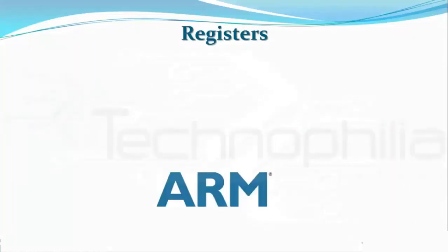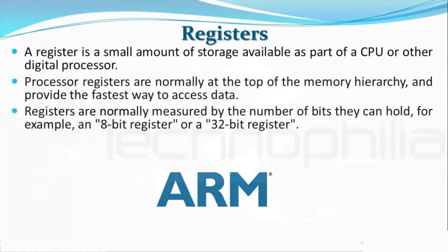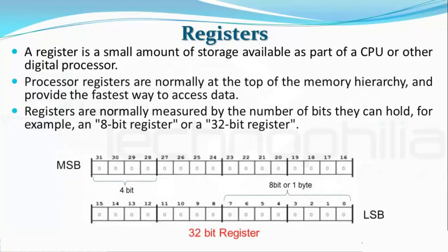Registers are the fundamental memory units present in a processor or controller. These are semiconductor memories and the fastest among all the memories present in a system. In the ARM Cortex-M3 microcontroller, all the registers are 32-bit registers. A user is allowed to write or change the contents in registers, but not in all the registers, because some registers are system-specific which can be read but can't be written.